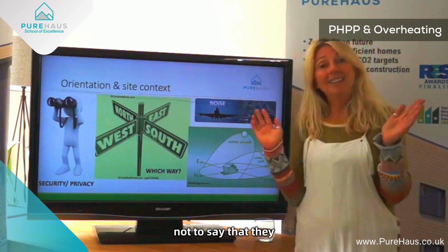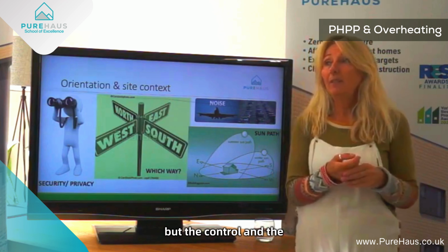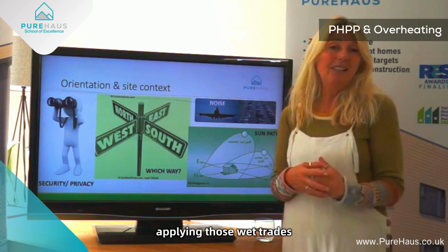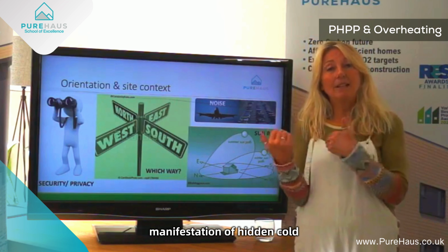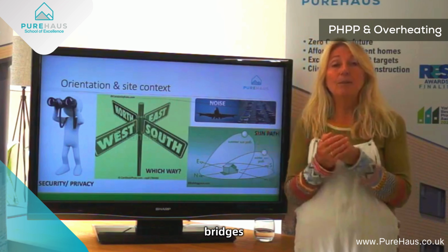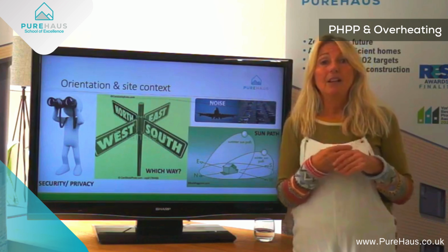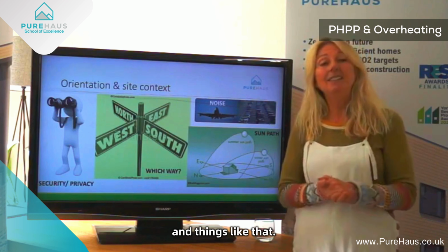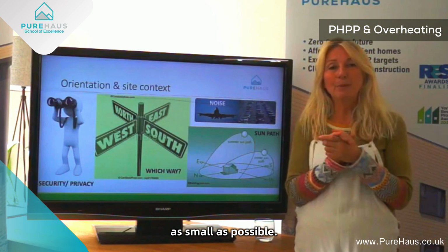However, not to say that they don't have a place, and absolutely they do. But it needs control and discipline on site in applying those wet trades, to ensure that we don't have heat and cold bridges, where perhaps we've got mortar droppings on ties that aren't thermally broken in the cavity and things like that. We want to try and keep those cavities as small as possible.